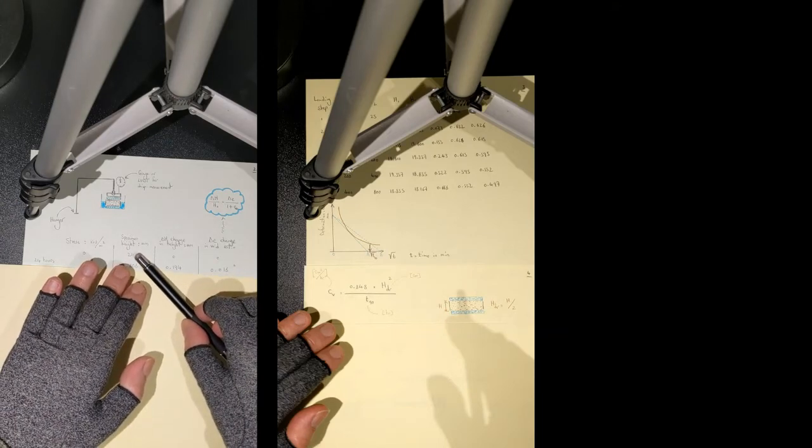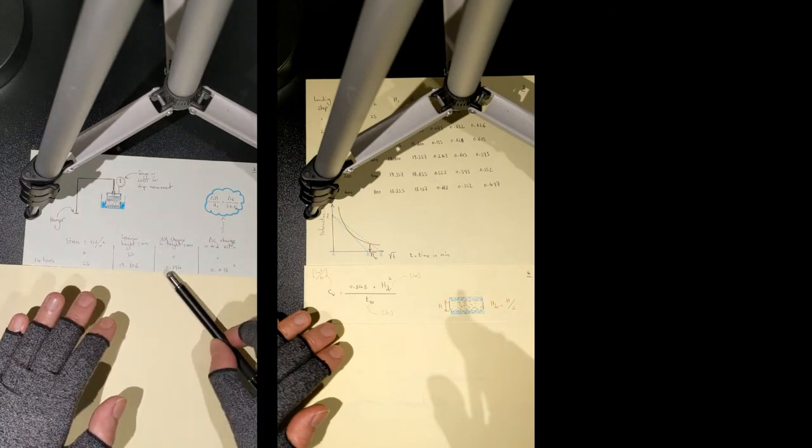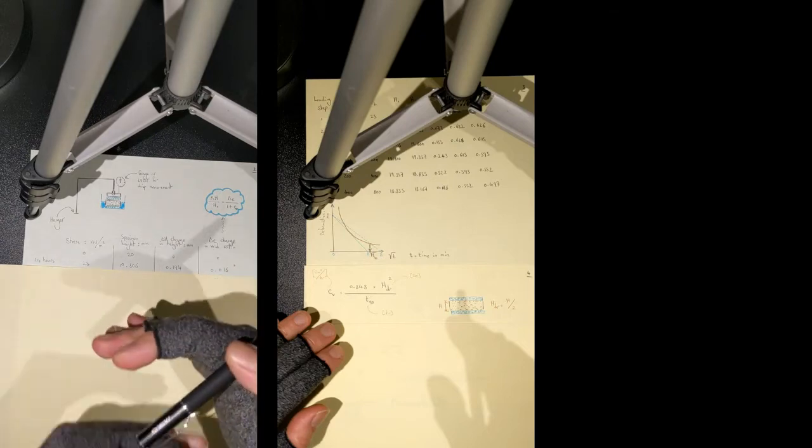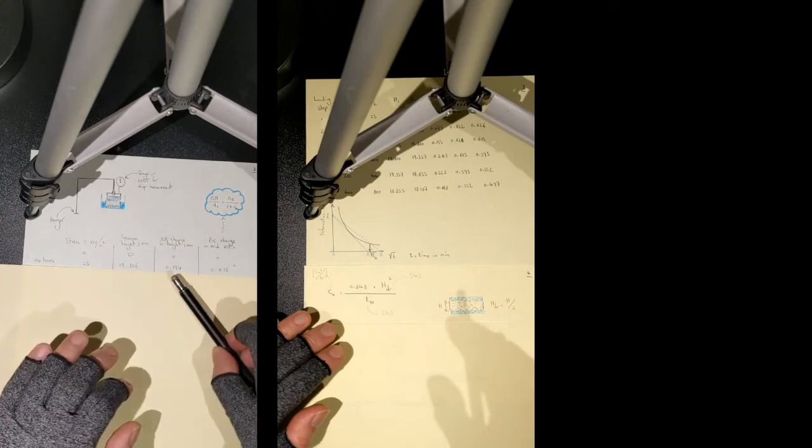Now, after 24 hours under 25 kPa, the specimen height goes down from 20 millimeters. This is strictly speaking an example. It can be anything really, but this is the example. It goes down from 20 millimeters, let's assume, to 19.806 millimeters. It means that the dial gauge reading is 0.194 millimeters. The specimen has settled or subsided after 24 hours by 0.194 millimeters.